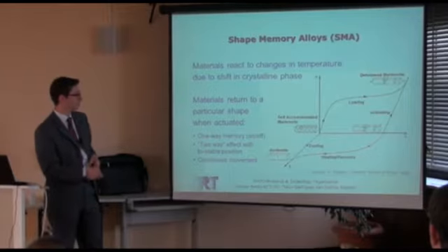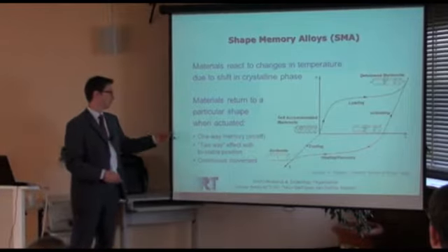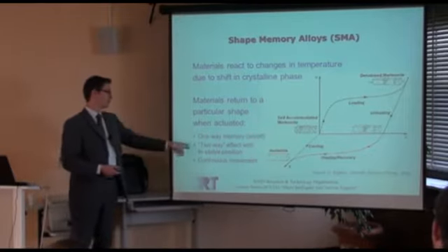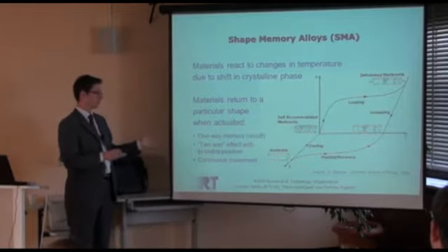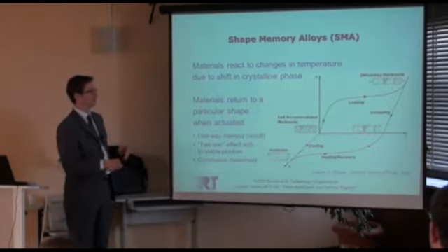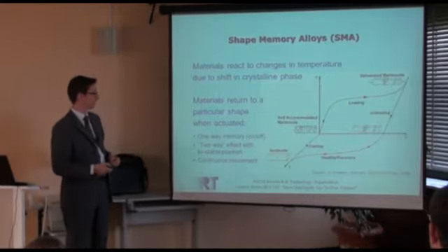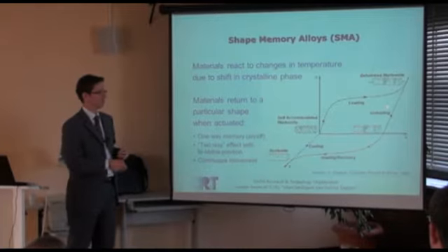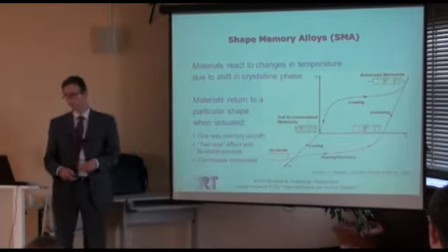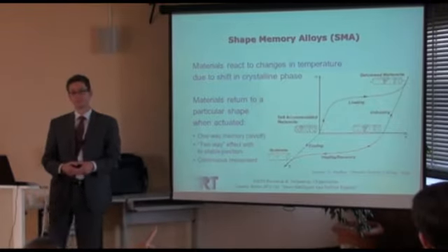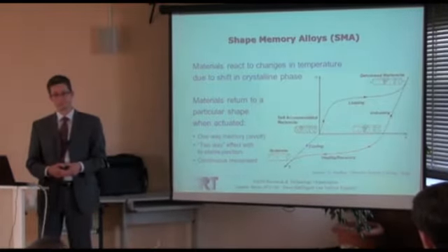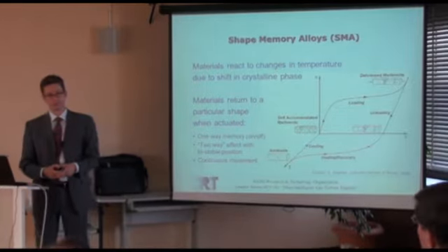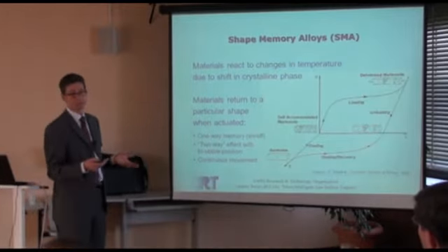They've got different principles for actuation. You've got a one-way memory, so just an on and off state. You've got a two-way position, so bistable, where you use these two shapes in the actuator. Then you can have continuous movement as well, so you're in between. You would form the shape up at the right-hand corner. That would be the shape you would form originally, and then you would actuate it to get the other shape, or vice versa, or both. It depends on the temperature level.